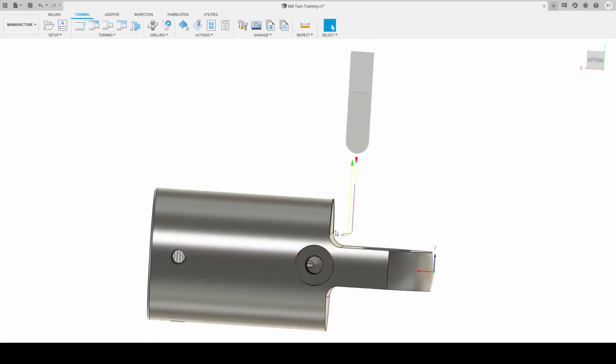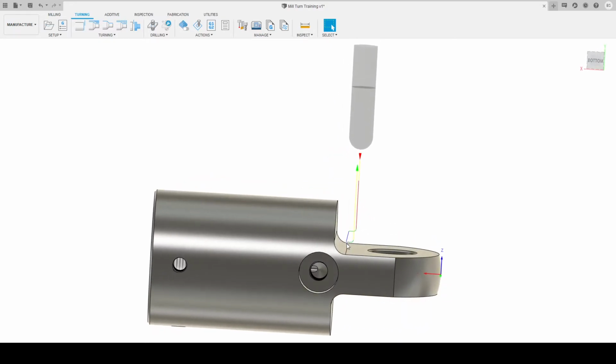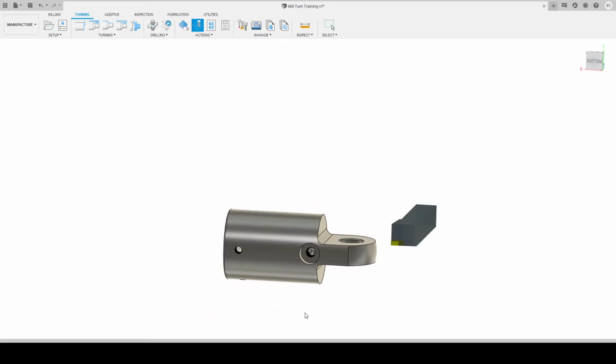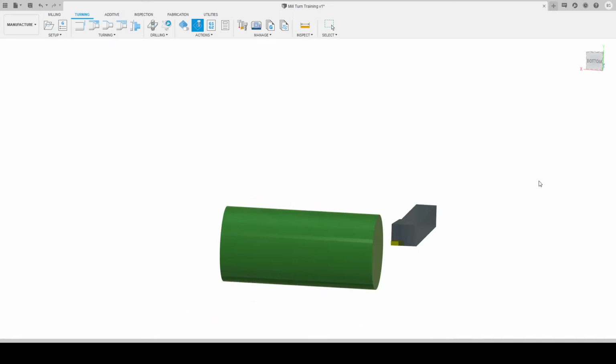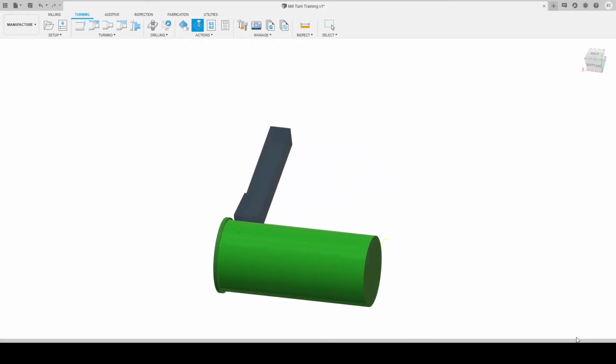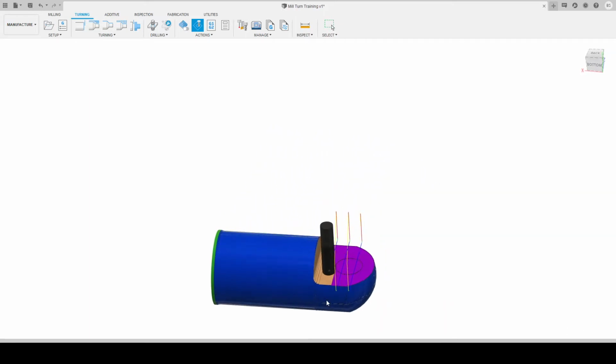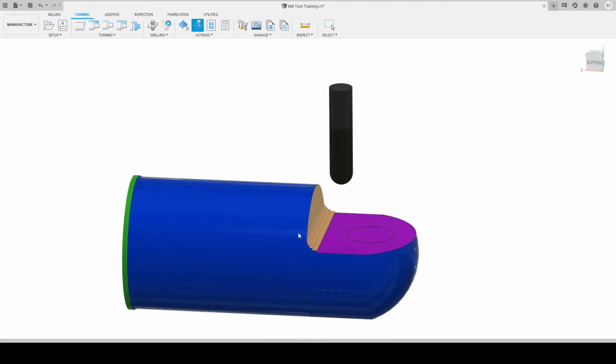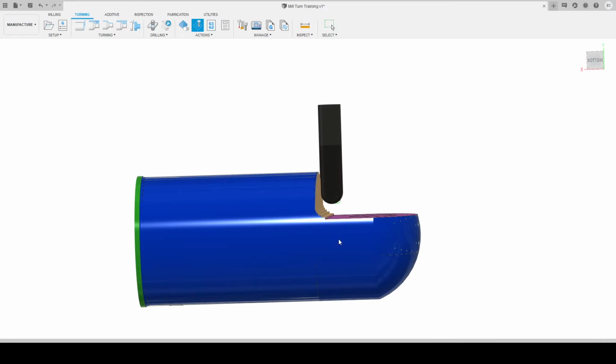So not bad, but we need to be machining to the floor. So if we simulate this, I'll show you what we get. We'll turn our stock on, simulate it. We'll just jump through to the last toolpath. So we've cleaned up the floor. Okay. We're going to come in with our ball mill, but see how it's not going deep enough?